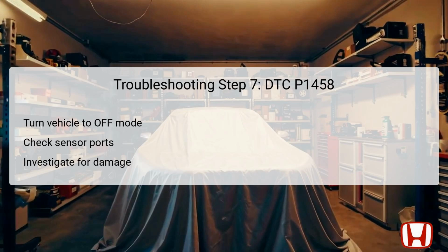3P connector. This reset enables you to conduct a visual inspection for blockages or damages at the FTP sensor ports, both on the evap canister side and vent side. If any blockage or damage is discovered, that can directly impede the sensor's functionality and cause improper pressure readings. Address these issues by either clearing any blockages or considering replacing the FTP sensor if necessary.